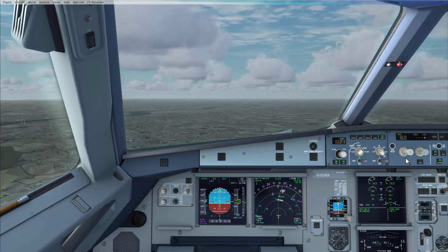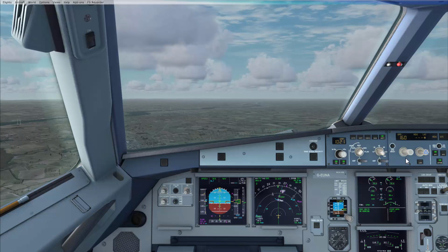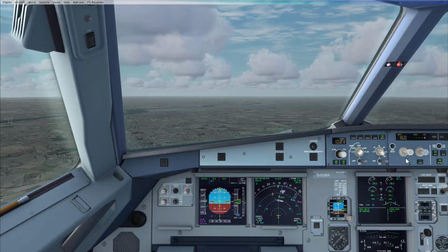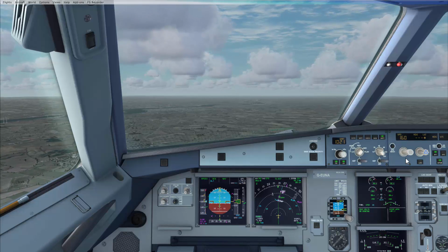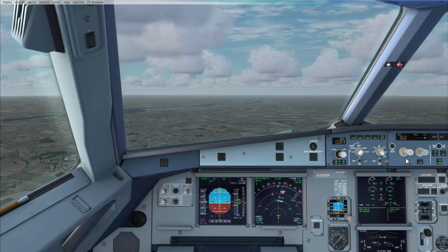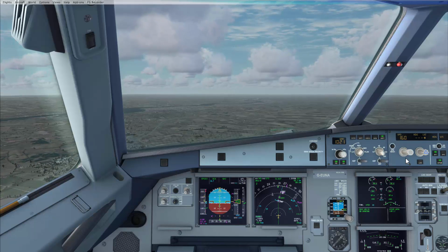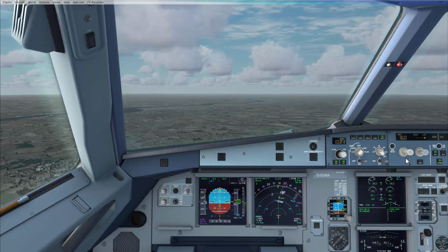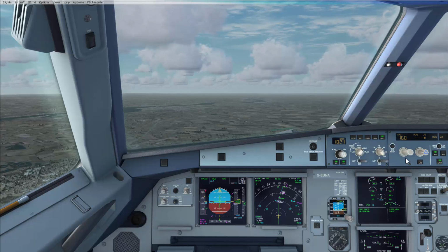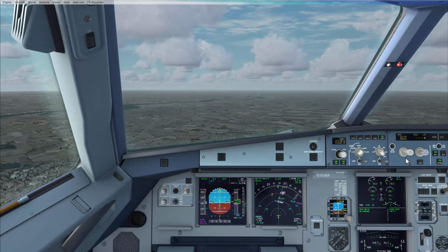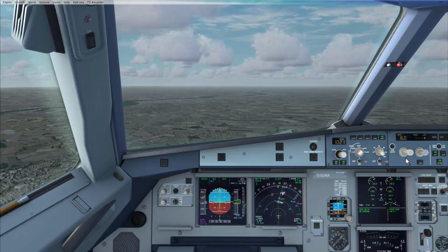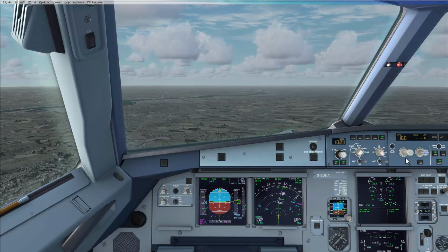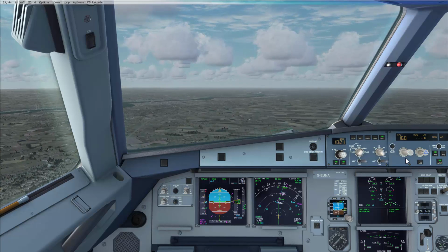And if we trigger the alpha floor setting, our Airbus goes into Mr. Super Health and Safety mode and throws the throttles fully forward to get us away from a situation where we may inadvertently stall. So although this isn't a process which is part of managed settings, it is an approach apparently that's used by real-world pilots, realizing that the managed numbers are just a little bit too close for comfort. They'll manually override, and that's what we're simulating here.